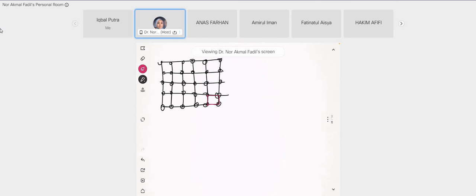An imperfect structure is when we have dislocation. Okay, one of the examples of dislocation is edge dislocation. So we define this as an extra plane put on the upper block, the material block. So it won't be inserted like this. It will be inserted like this. This one will be an extra.